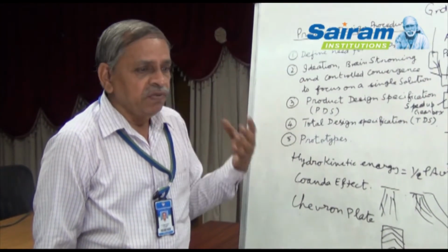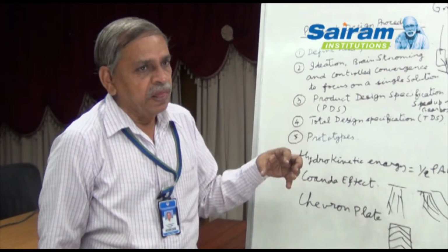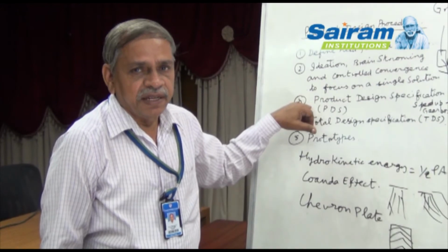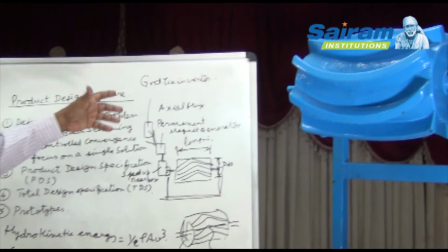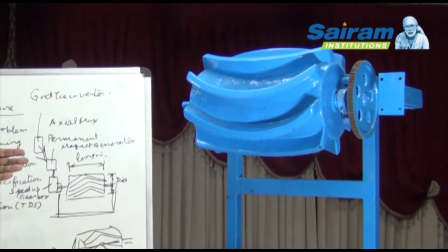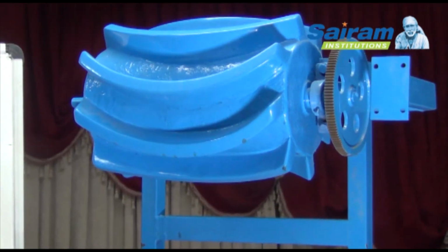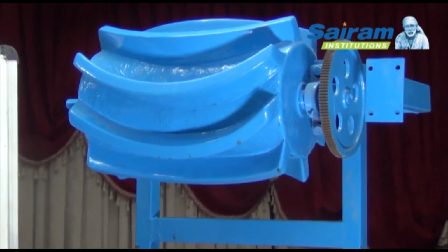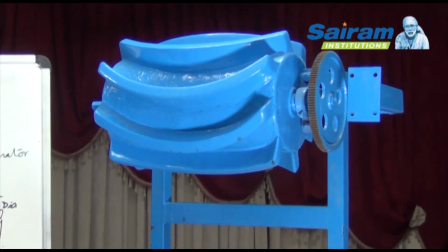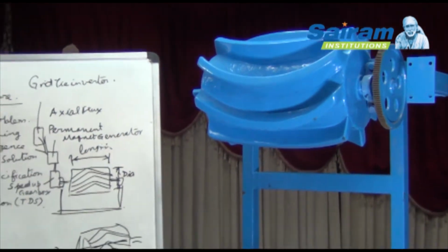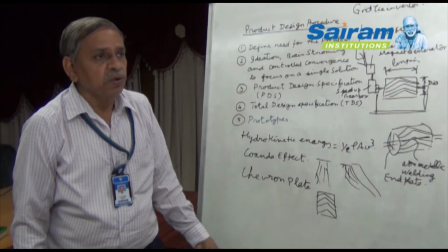To summarize, what we do is we have to develop the prototype after that. So a product design specification is very essential. So we have to define what is the diameter of this turbine, what is the length of the turbine, and all. So here we have developed a 400 millimeters length and a 300 millimeters diameter turbine. So at the end, we have placed a gear. There we'll have to place a permanent magnet generator, which will work at a very low speed. We need to have a speed up gearbox, because when we put it in water, it is going to reduce the speed.